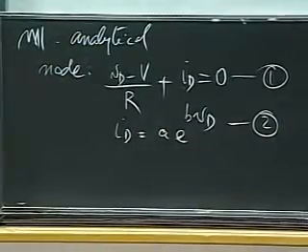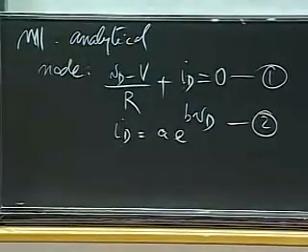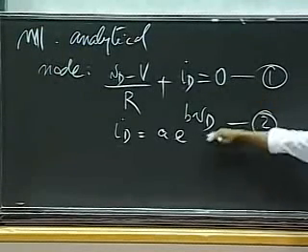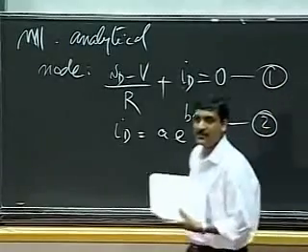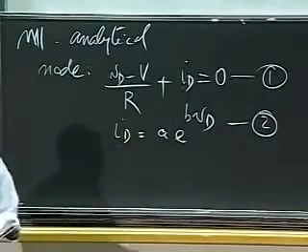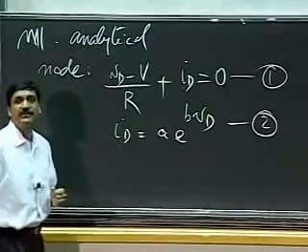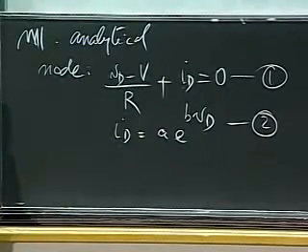You guys can now go ahead and analyze nonlinear circuits. You get a bunch of equations, a bunch of unknowns, go solve. I have two equations here. VD and ID are my unknowns, and I can just go ahead and solve for them. Now, in general, with nonlinear circuits, oftentimes it's hard to get a closed form solution. So you may have to use a bunch of methods. You can try a closed form solution, or you can try numerical solutions, or you can do trial and error.